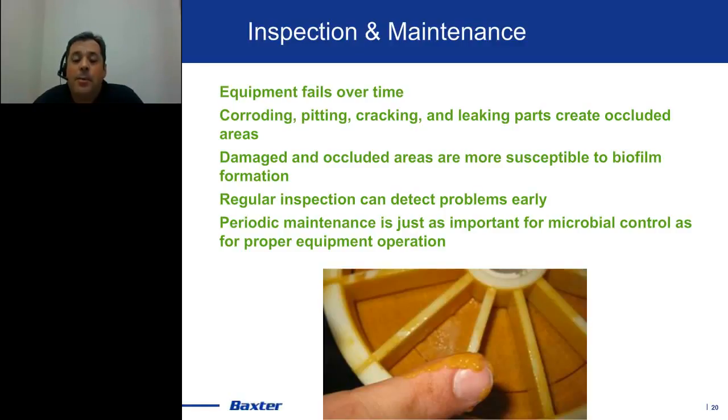So this is an opportunity, as I see it, to basically use this for microbial control, either educating those maintenance folks about the potential risks if they see something going on, discoloration, growth in there, or potentially having one of your microbial control folks walk the lines with them when they're doing their periodic inspections or maintenance, when they're opening up the system, have somebody who knows about microbial control working with them, educating them and checking out the different components as they're being opened up.